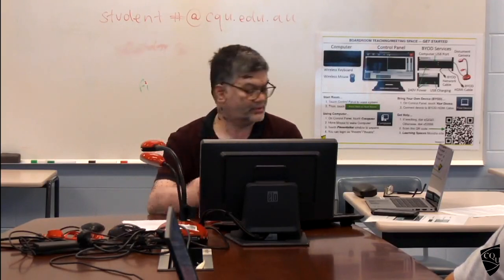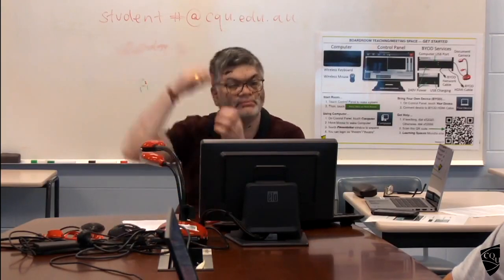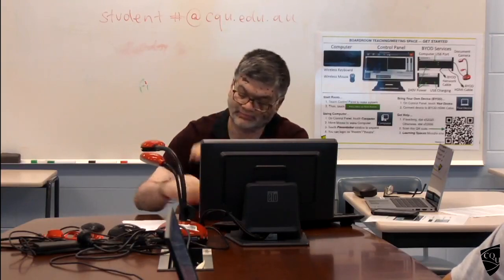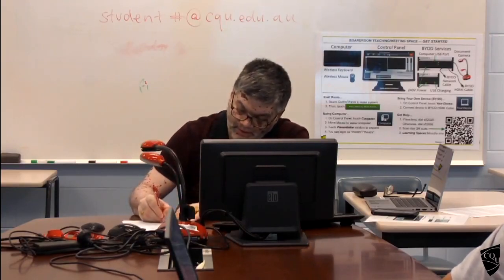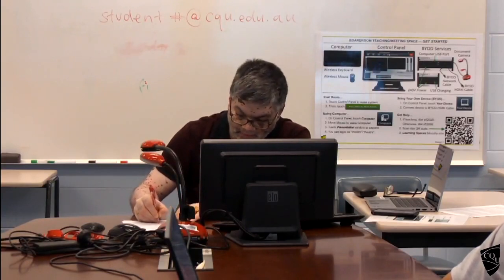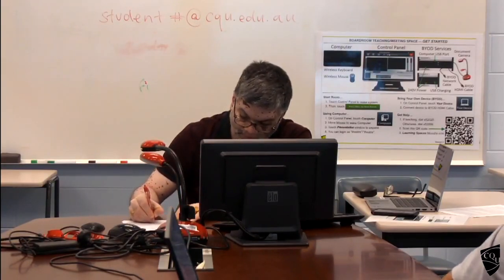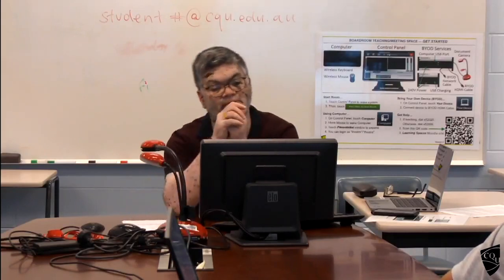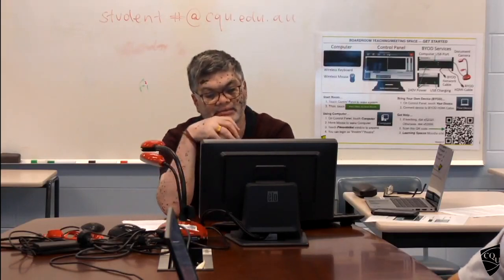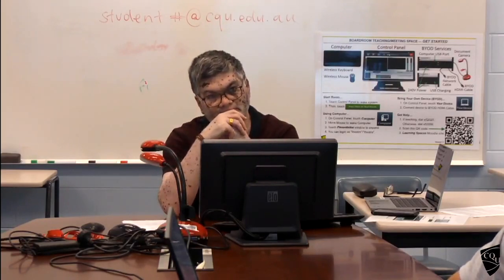I don't think that's any problem. The L effective, what is L effective? Minimum of ln plus d, and L. L is the center to center distance, ln is the clear distance. So you should be able to find out the effective length.